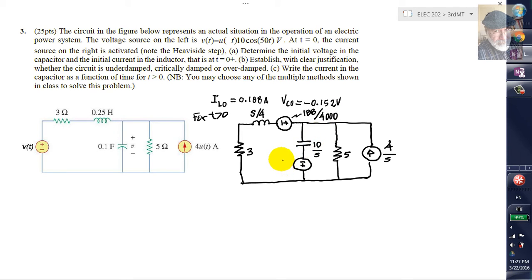That's why. And the value of the source for the capacitor is pointing downwards, which is the direction of the initial condition. It's the polarity of the initial condition in that capacitor. It's Vc naught divided by S. And I'm writing Vc naught as 152 divided by 1,000. And we are ready. Choose your reference node, the usual stuff as we do with MNA.